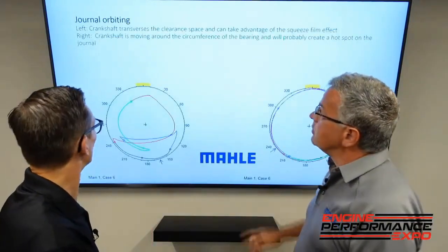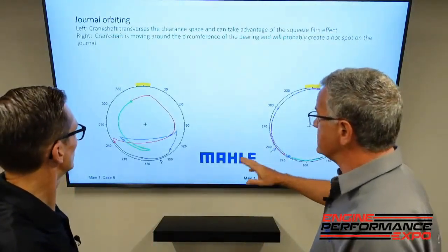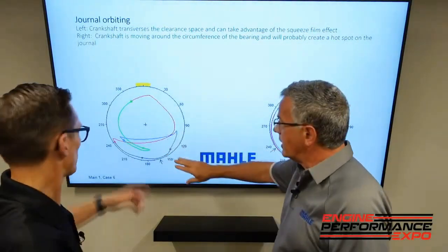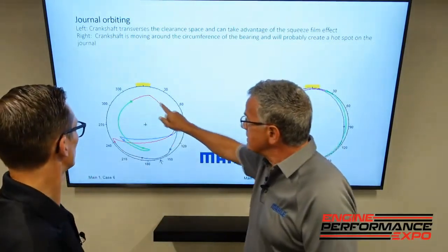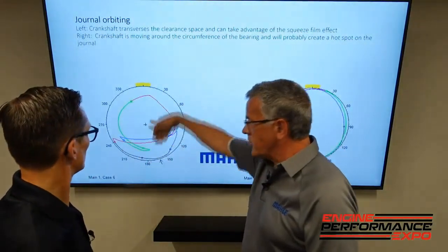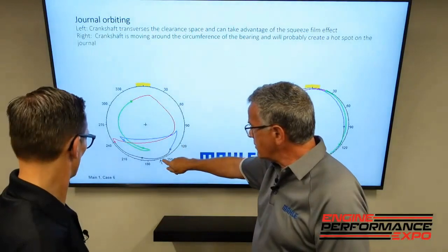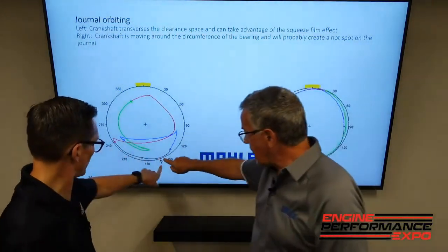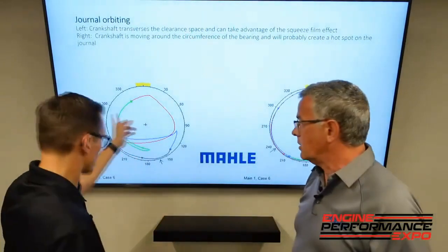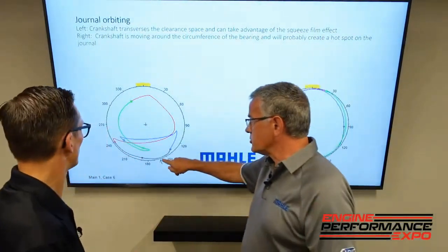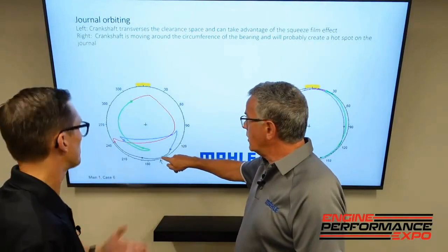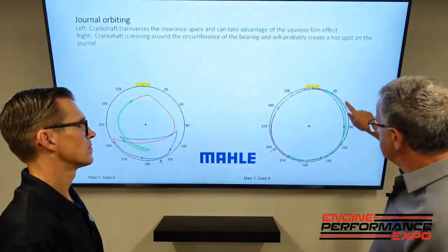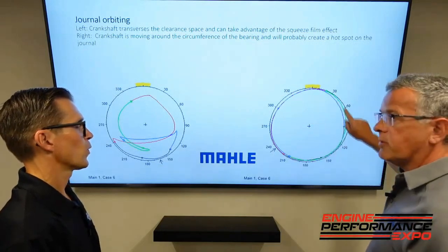Okay. So the perfect case scenario, this is a picture of a crank. This is a happy crank. Okay, there's space. As the engine fires, pressure is coming down, so you know this is going to be where your minimum oil film thicknesses are, down here. Right, that makes sense in terms of rotation. So this would be the highest pressure and the lowest film thickness. Okay, as that crank bends, now you can move it to where it's orbiting.